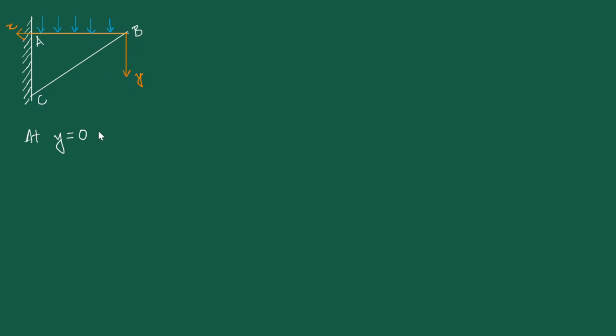For that, first of all, we note that nx is equal to 0 and ny here is -1. This is very, very important. Please do not make a mistake here, because y is pointed downward. For this top surface, the unit outward normal will be pointing upward, but that upward direction is the negative 1. So please don't make a mistake there.